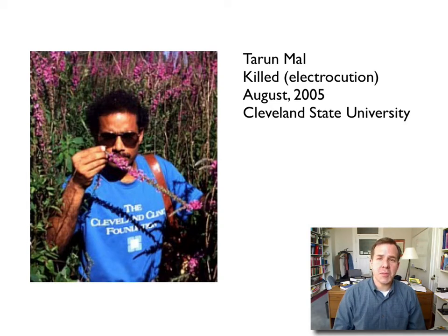They had three-prong grounded plugs, but for reasons which are unclear, at least to me, he plugged a three-prong plug from what was supposed to be a grounded light into one of those cheater plugs that allows you to plug a three-prong plug into a two-prong outlet. As a result, his light was not properly grounded. Under ordinary circumstances, that wouldn't be a big problem, except that there was an internal fault in the wiring of his light, which meant that the housing of the light was actually live.